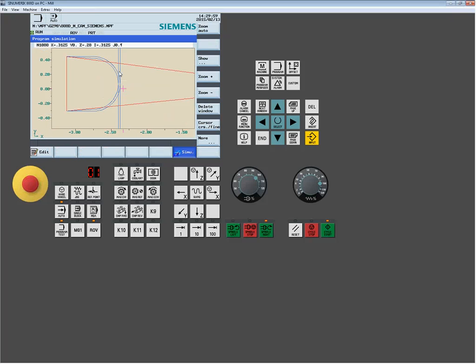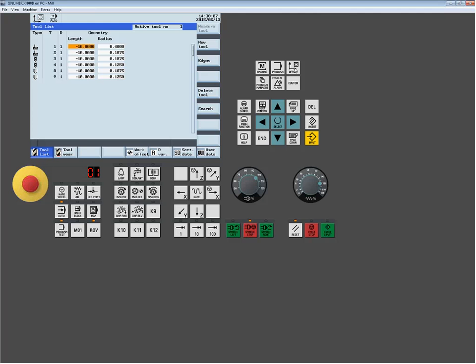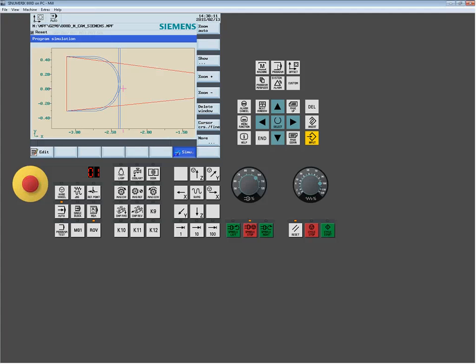Let's break for a second because I do see a couple questions coming in. Can I search by a block? Yes, you can. When I did that search command, I have this search field, so I can type in actually anything unique here. If it was a T measure tool, they are not available when you're in ISO mode. We're trying to make this run more like an ISO-based program. So G40, G49, standard header statements, G80. Tell it to do a tool change. We have a tool change protocol right here.